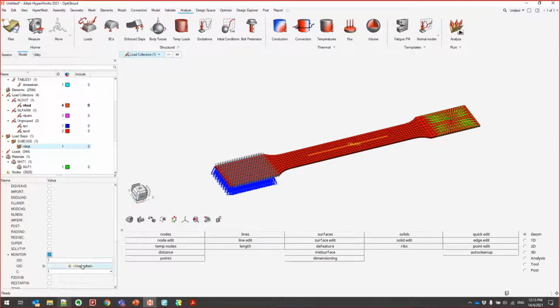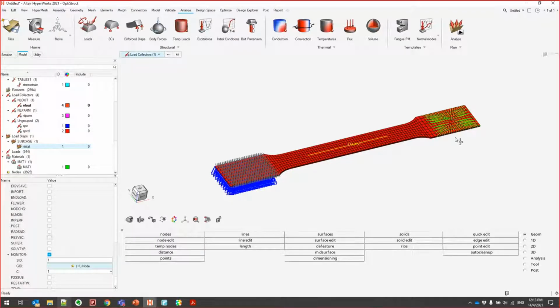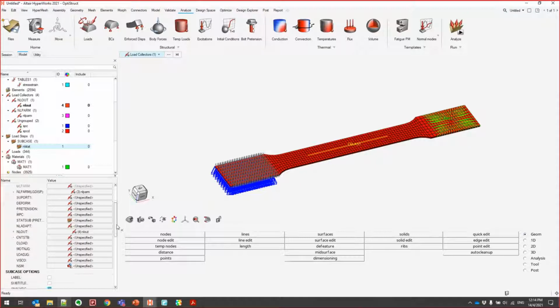Just turn it on, and you can specify which grid to look at. So I'll just look at grid 11 because this is the grid that is being pulled, right? So I'll just look at grid 11, how you progress over the entire simulation. Okay, so I'm just going to track direction 1, which is the X direction, right? So that is more for monitoring purposes. It wouldn't affect the run. Okay, so large displacement, yep, that's all. So I'll just output now.